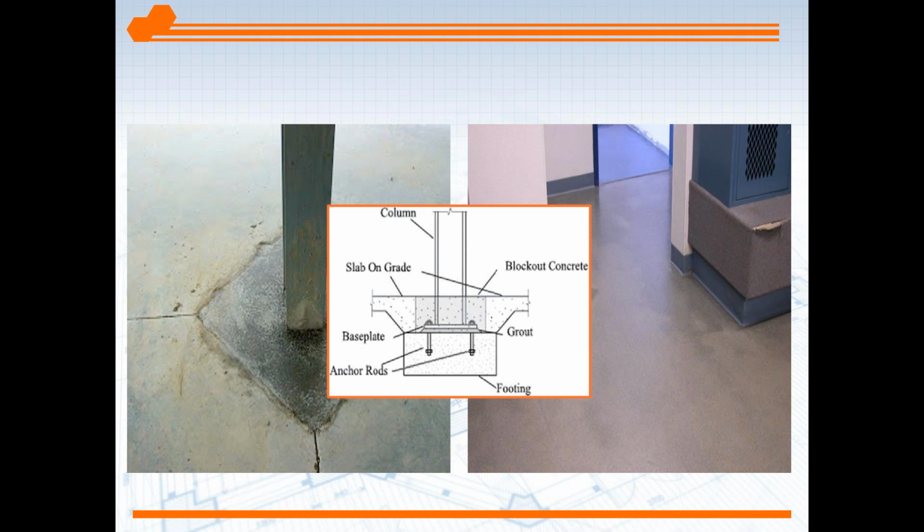And if you take a look at the picture on the right, you can notice coming in the doorway and next to the locker, there seems to be darkening. So it looks like they've got moisture issues throughout this slab. So typically when you're installing a concrete floor like this, you've got possibly a moisture vapor barrier under the concrete, but no one thinks about that concrete blockout being a moisture source damaging the floor covering.